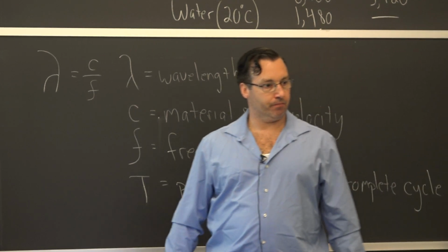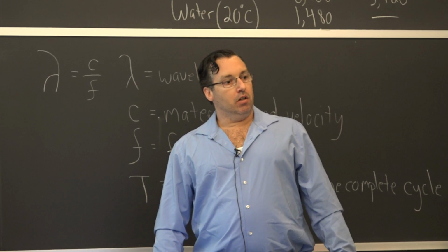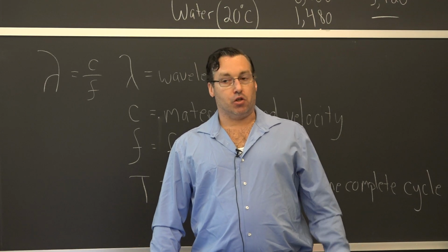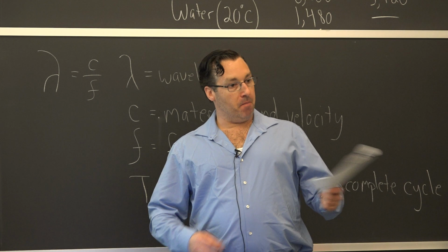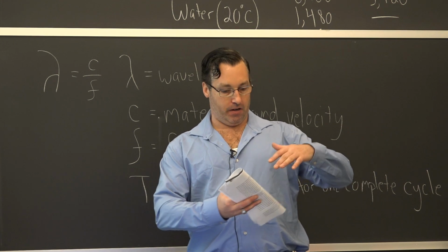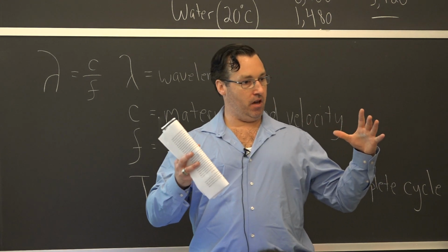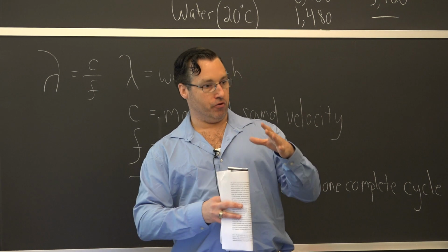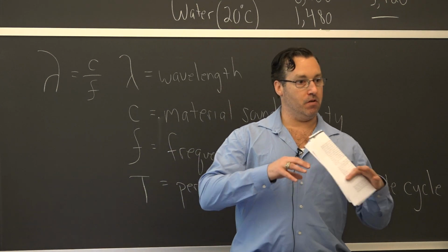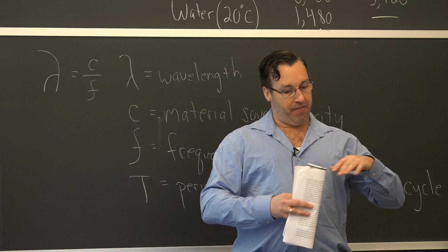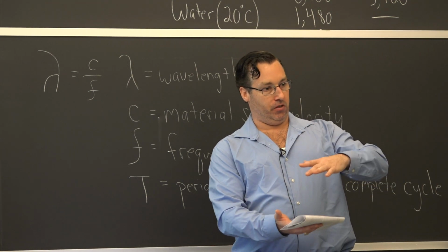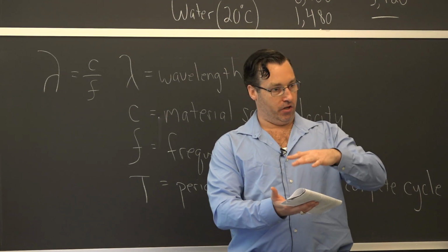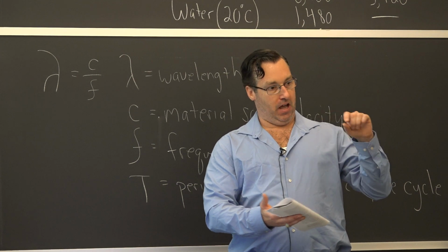So why don't people go to extremely high frequency? If you could get a 100 megahertz transducer and sensor, yeah, use it. For carbon fiber composites, if you're trying to find a delamination or a debond, they do go up to hundreds of megahertz. That's where it's dissimilar materials in intimate contact with each other, if you're looking for a delamination.